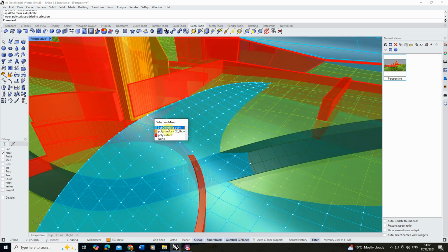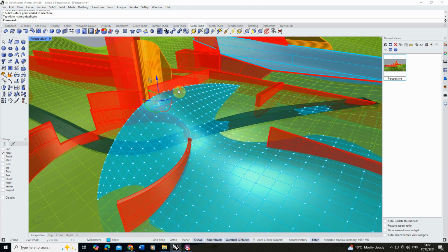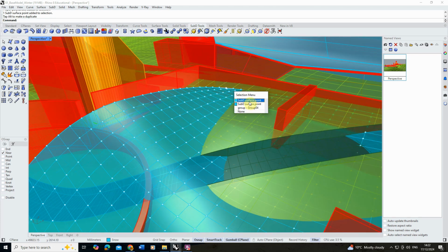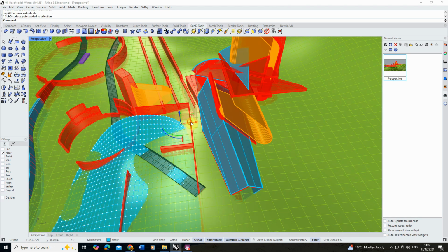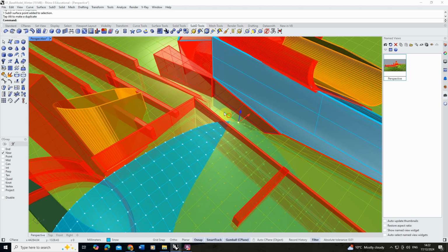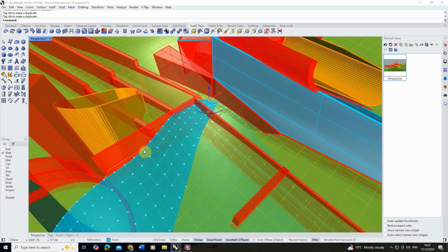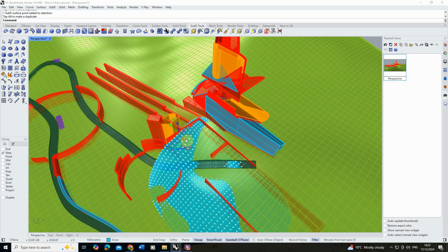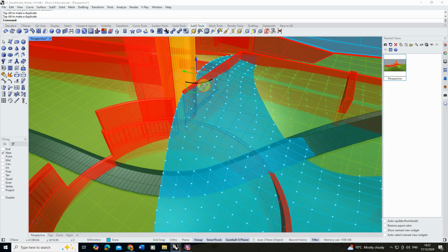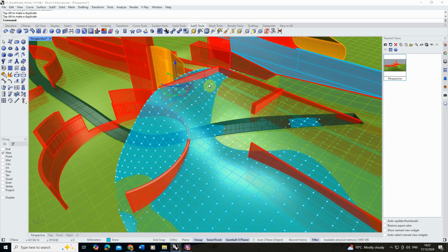And we're just wanting to create these sort of mounds of snow that look like the snow has pushed up against these walls. Now you might need to stretch and pull the terrain over, so I'm just going to do that in this case and for this one. You might also find that the radius you're working with is too big, so if you need to lower that down, we can go back to that soft transform.